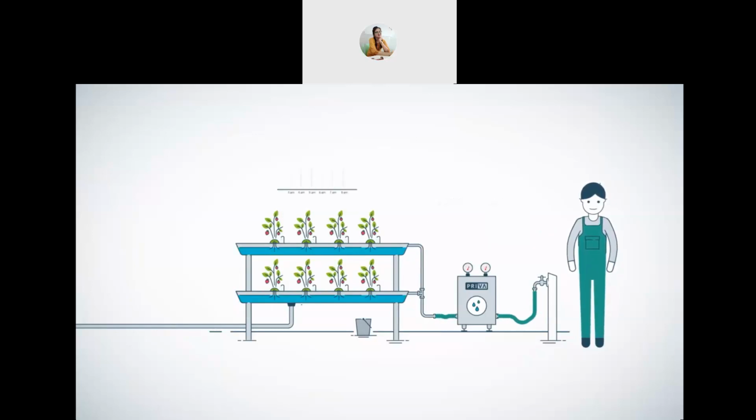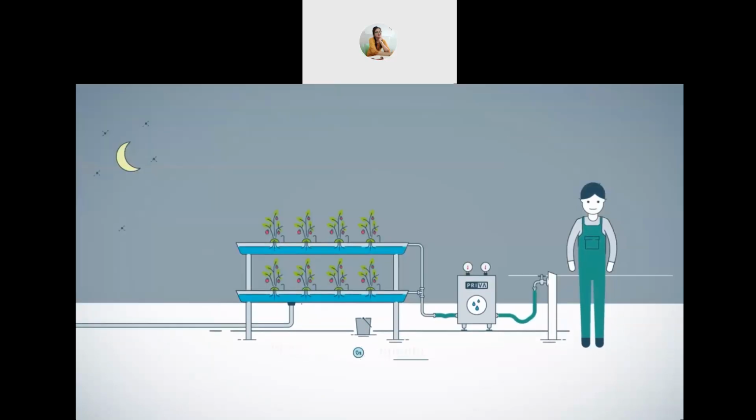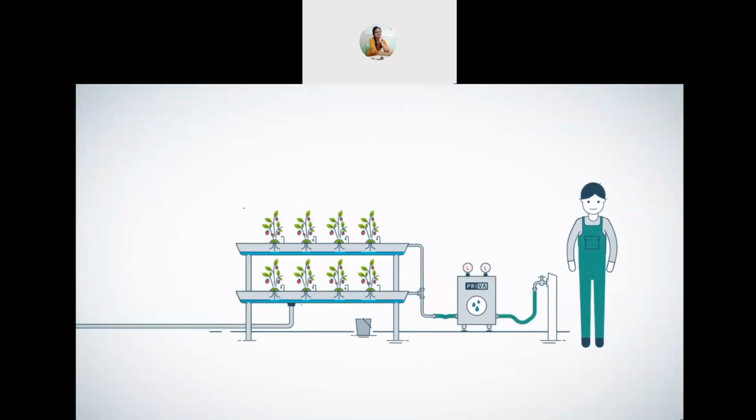When the scales or sensors indicate a fast moisture level drop in the morning, the system knows that the plants are consuming water and will automatically start irrigation, perfectly timed and quantified. No more water stress and guttation. During the day, the system will ensure an optimal balance between water and oxygen with minimal drainage. And at the end of the day, it will make sure that irrigation is done in time to achieve the desired overnight dryout. Priva, increased production by optimal water dosing.